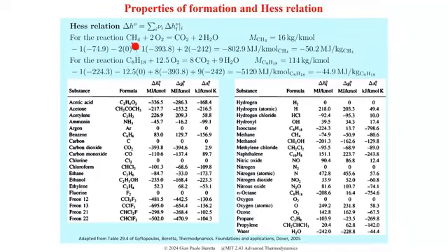So the simplest model for oxidation of the fuel, complete oxidation of the fuel. And so the stoichiometric coefficients are -1, -2, +1, +2. Then you pick from this table the values of the enthalpies of formation. So, for example, you look for CH4, which is methane, here, -74.9. So that's where you get this number. The elemental species have no value for the property of formation. It's 0 for them. So you can recognize them here.